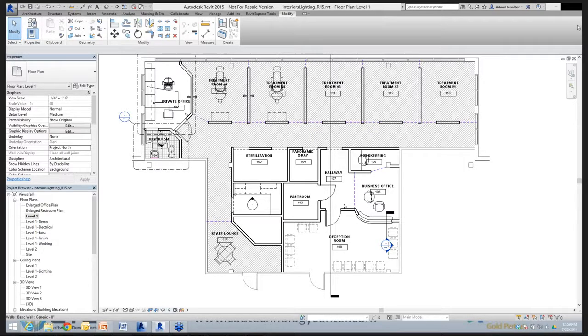One thing to note with the COBie tools, whether it's the Autodesk COBie tool or our CTC COBie tool, they add COBie specific parameters to the families. There's a button you click to add parameters. So a lot of that information gets manually included.